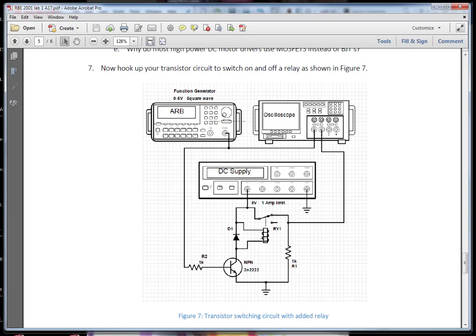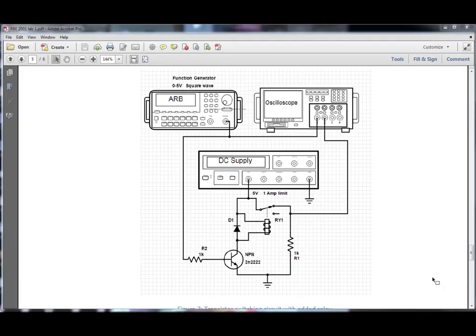But this is interesting because this has a clear case, and you'll actually be able to see this switch closing. So in this configuration, you can see that when the voltage goes high here, and this transistor switches on, the coil activates here, and that pulls this down to an open circuit. So the measurement right here is going to go to 0. When the coil isn't activated, then this is connected to the 5 volts right here, so this should be reading high.